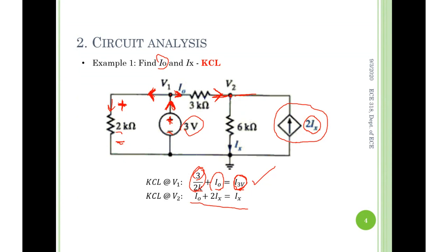The arrow in the diamond means current. How can you tell this source is relying on the symbol, the circuit component symbol? It's an arrow rather than polarity, positive and negative. That's why this is a current source, and also this is a current dependent current source. Very good. Very, very clear logic.